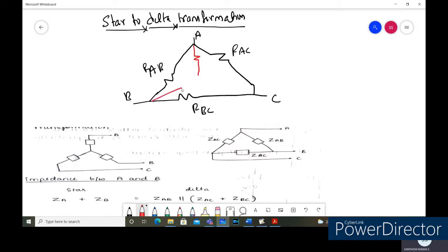Between the nodes A, B and C we can replace it like this. Since these are resistances, we call them RA, RB and RC. This delta network can be replaced with the star network, which is sometimes also called a Y network. Afterwards we can apply the concept of series parallel combination, reduce a complicated network into the simplest one, and find the equivalent resistance between the respective terminals.